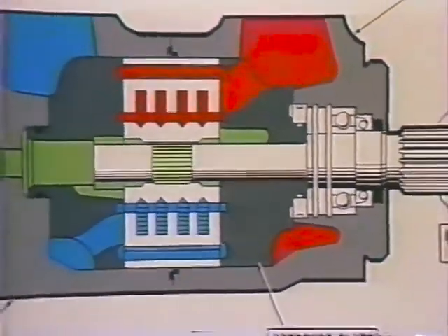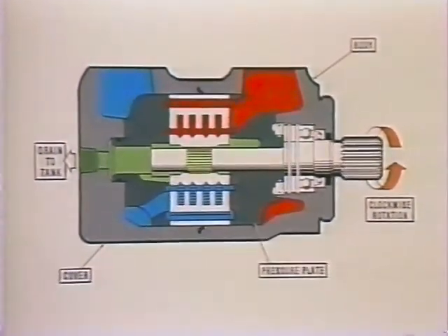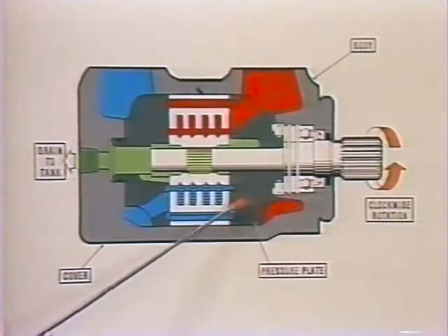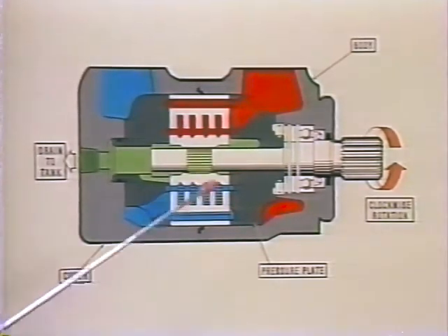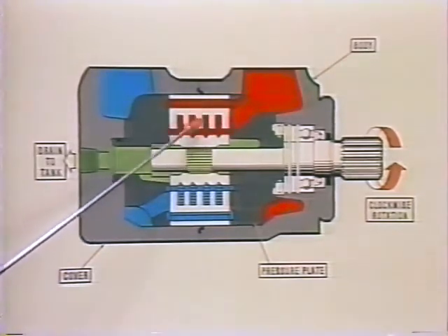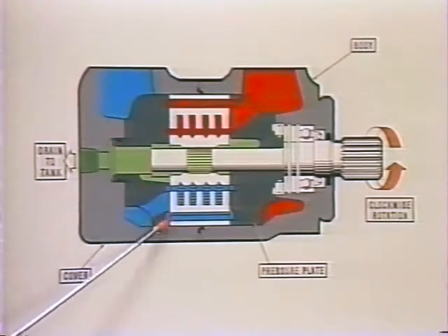Now here's an illustration of a high-performance balanced vane motor. It operates at higher speeds and pressures. Like our intravane pump, it features a pre-assembled, pre-tested cartridge for speedy field replacement. We can see that oil coming in at this port directs high-pressure oil to the top and bottom of the vane. On the discharge side, we see low pressure, top and bottom. Thus, we're balancing out the pressures, top and bottom of the vanes, to reduce vane tip loading.